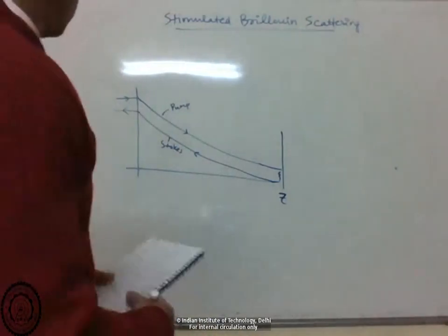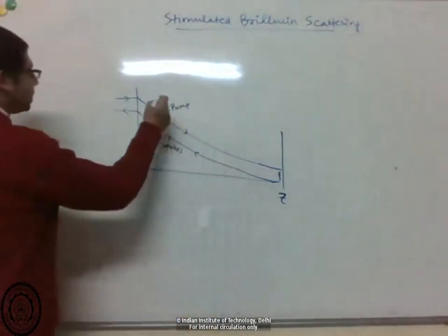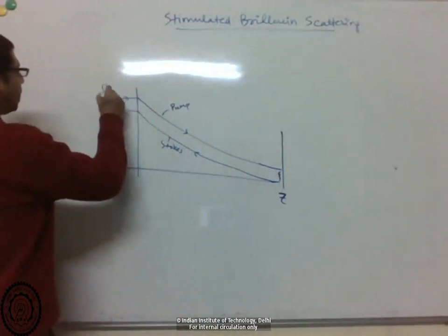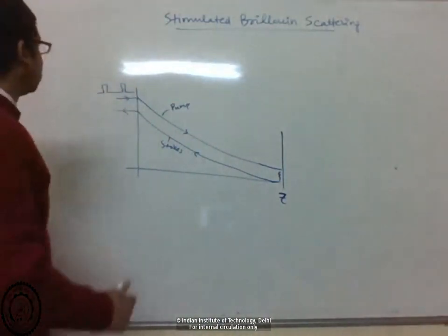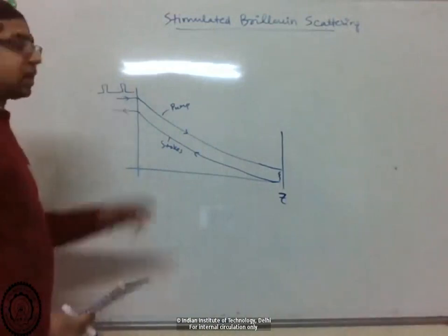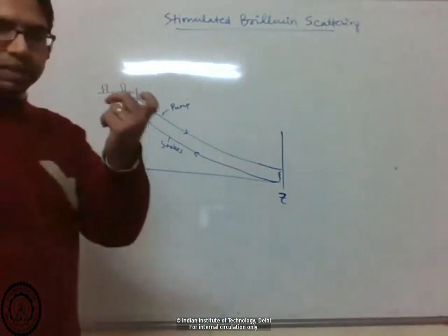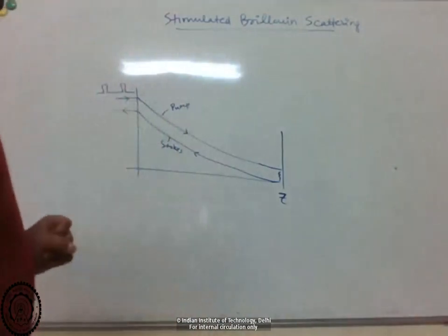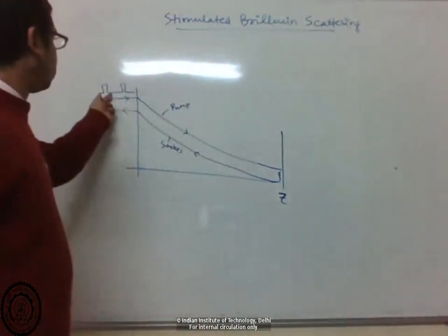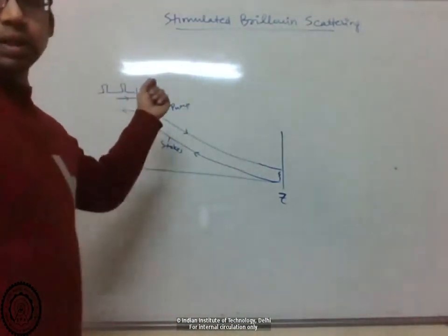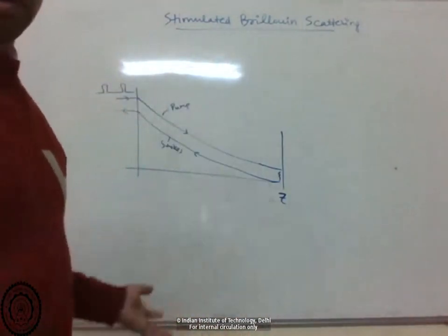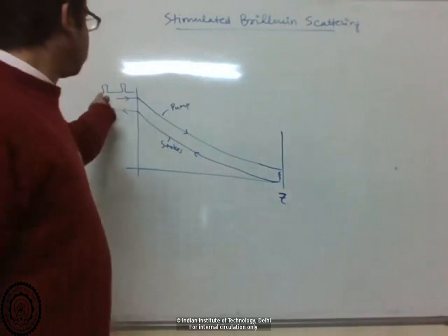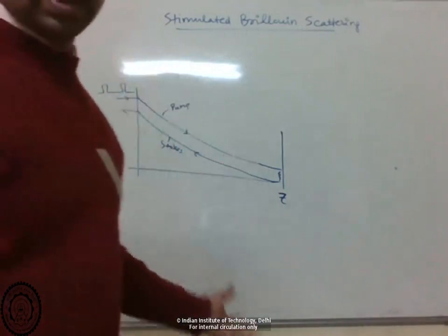But for optical communications, for example, you would send in bits. So there will be optical pulses of a certain duration, and the higher the data rate, the shorter this duration keeps going. And we know that if you have pulses in the time domain, that means in the frequency domain you have a bandwidth, and the smaller the pulse width, the broader the frequency spectrum.